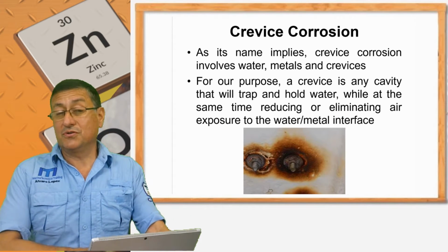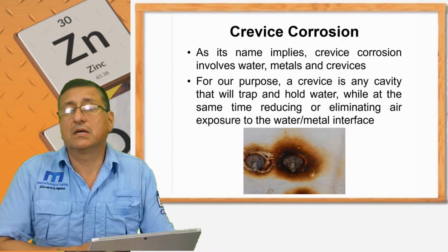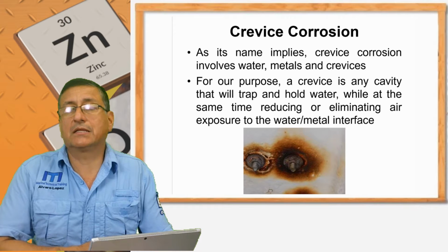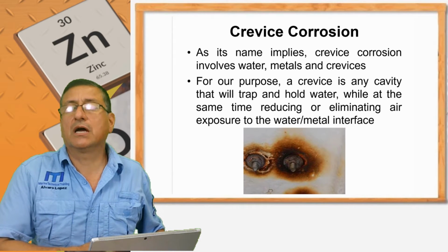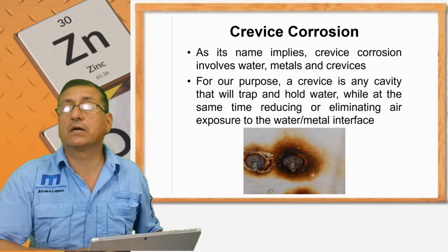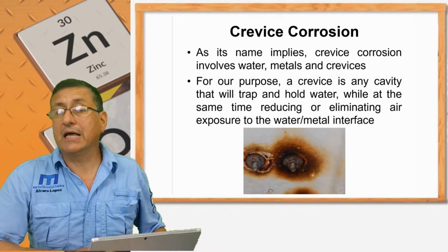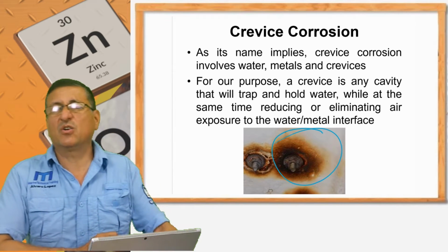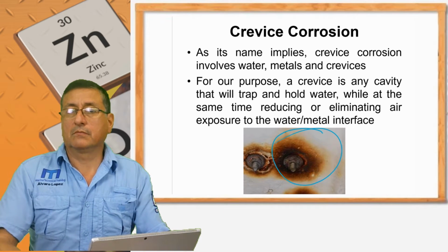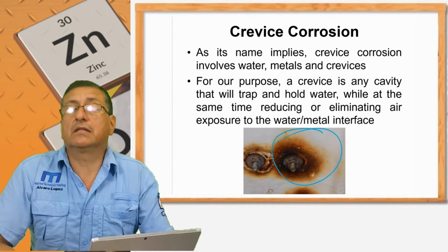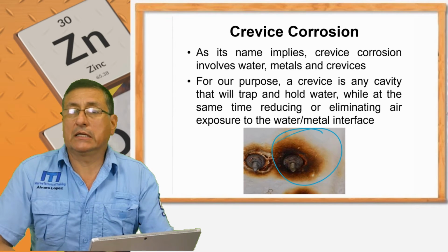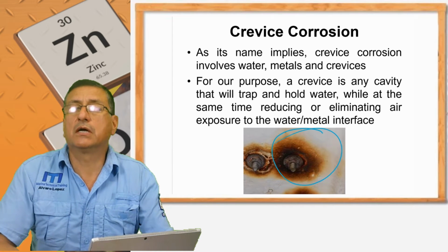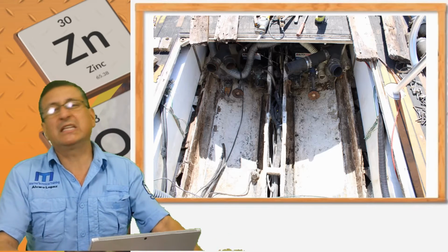Okay, and crevice corrosion. You remember we explained, be careful with the hardware used in your boat. The hardware can attack the boat. You might say, no, because my boat is fiberglass. Yes, but the fiberglass can be damaged because you use regular steel on the bolts, on the hardware. Those regular steels with salt water, the marine environment, are corroded, and at the end of the day the fiberglass is completely oxidized, delaminated and destroyed. You remember the example of the boat where the stringers were completely destroyed because people used regular hardware in the motor mounts, and those lag bolts destroyed the stringers, and the humidity penetrated them.